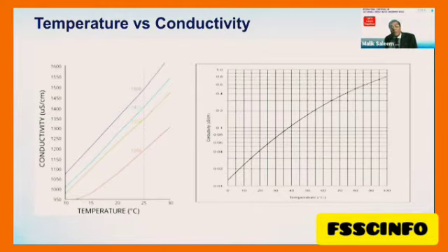It is always better to measure the online or flowing water pH at the duty point. You can have a beaker, keep the water flowing in that beaker and put the electrode in it, and then you will have a representative pH of your stream.